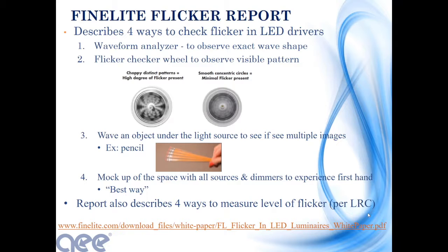In the Fine Light Flicker report, it describes 4 ways to check flicker in LED drivers. If you're an electronics engineer, just get out your waveform analyzer and you can observe the exact wave shape. Other ways, where you're not an engineer, maybe a flicker checker. We used to have these Motorola flicker checkers that I still have. I suppose some people also have them maybe in their closet.